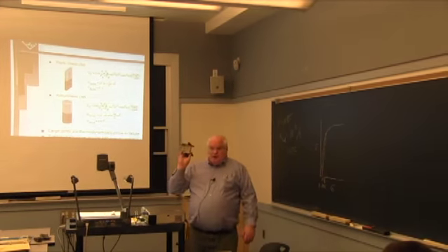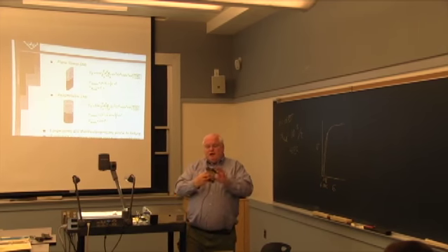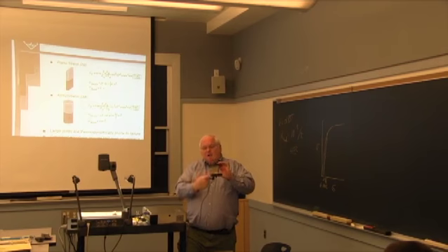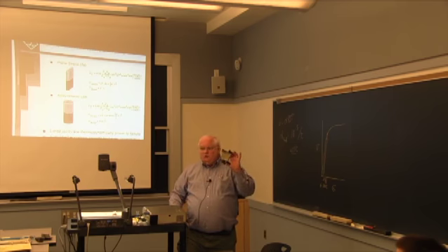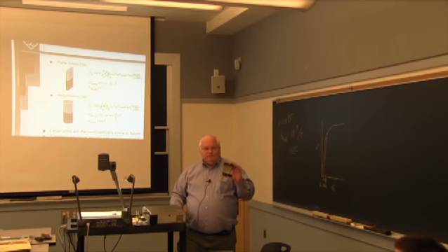And if I take this, shoot, I got temperature gradients on this thing. If you do the modeling, you've got 500 degrees between here and here. I mean, this is attached to the stator and this big massive thing, and the hot gases are hitting right here in the center of this. You look at the thermal model, you got a big hot spot in the middle, and then you got cool spots down here. How do you keep the ceramic from just forming a dried riverbed pattern and flaking off?